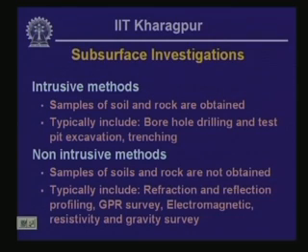These subsurface investigations can include intrusive methods, in which a borehole is drilled typically through the different geologic units, or it could include test pit excavation and trenching, and by looking at the different features on the walls of the test pit and trenches, one could correlate different geologic units.